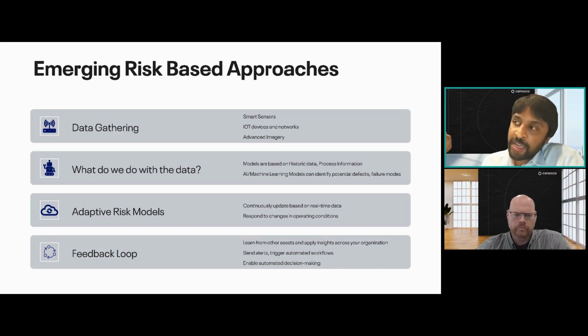By performing inspections on a limited number of tubes, we can extrapolate the results across the entire tube bundles and plan future inspections much more confidently. So these are some capabilities that are already available, Tomislav, and we will be looking to enhance, especially with AI ML algorithms, and especially our experience with AI ML algorithms with Air 3D and other aspects as well.